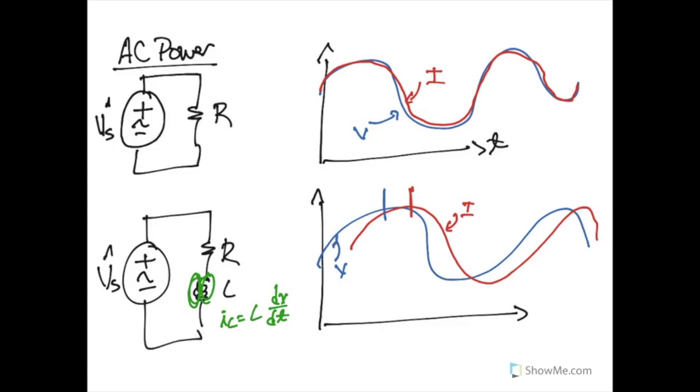So in our example up here with our resistor, both peaks came along at the same time. Depending on the size of this inductor and all the components that are involved with it, the peak of this voltage wave and the peak of this current wave might actually have some sort of time dependency between them, and they might be off. And this has implications for all the electronics and the motors and the components that we want to drive in this system.